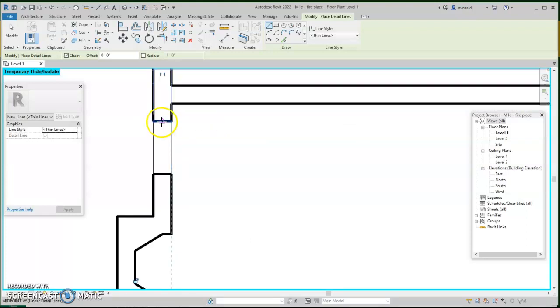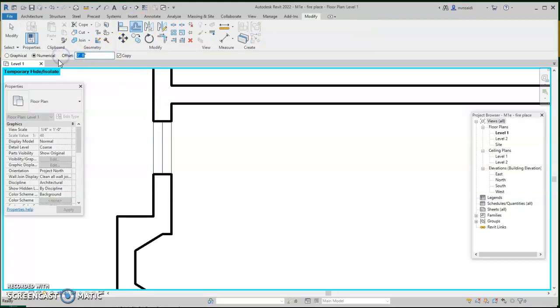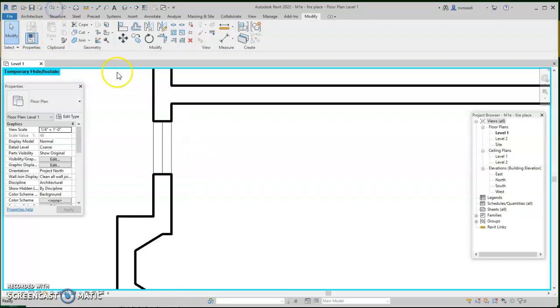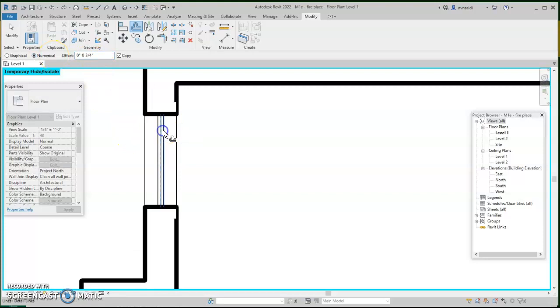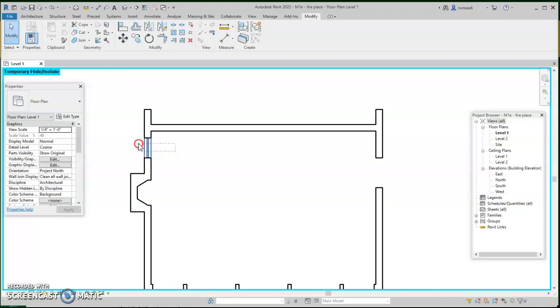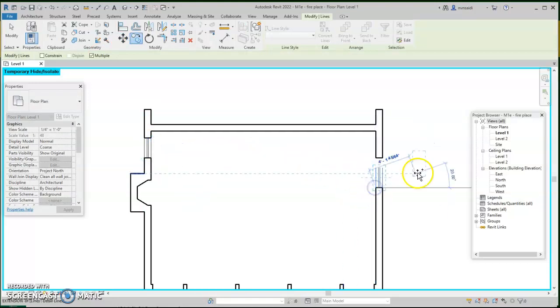And then I'm going to zoom much closer, go to the middle, quickly take that and offset it an inch or 3/4 of an inch. I'm going to go 1 inch, see what it looks like. And then I'm going to offset it the other way. And then I'm going to look at it, and I say, I like it, but not as much. Let's backtrack and offset it 3/4 of an inch. So I'm going to say 0.75 of an inch, goes to this side, goes to that side, and then I remove the middle. Now, I can actually take the same thing, copy from here, and place it here, and just simply extend